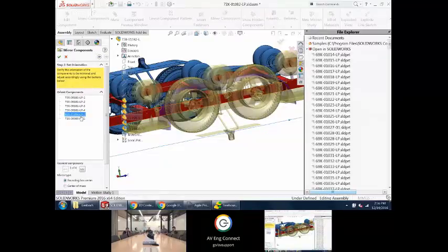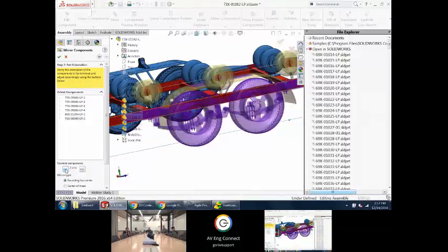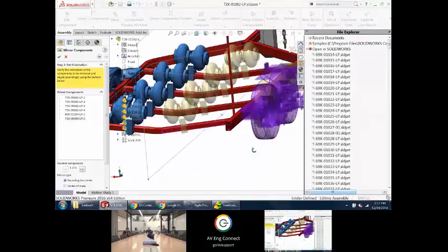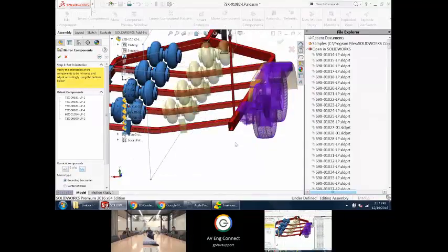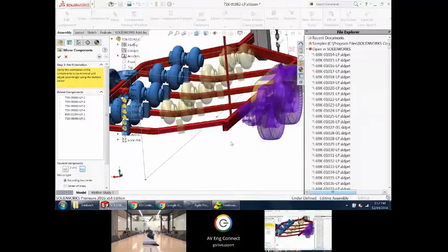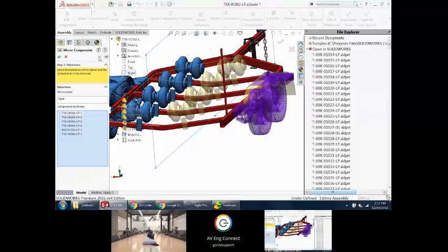So it puts me into this where it shows me the position they're in. I can actually toggle the position on this thing about the X, about the Y, about the X and Y. So there's 4 different positions. Sometimes it'll look like it'll work. Sometimes it will look like it won't work. If it works, then all you've had to do is it guessed wrong on the orientation on the other side. If you can't get the thing to fit for the life of you, chances are you need to have a left-handed version of that. So if we go back one level